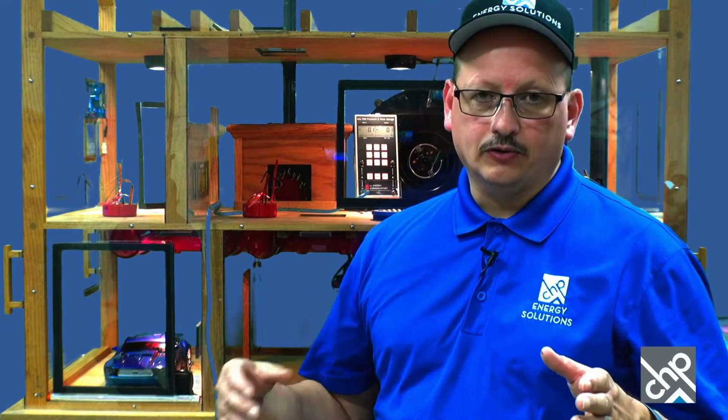So what I did is I set up this dominant duct leak test, and I measured the pressure. All I needed was a manometer. Like I say, I turned everything off, did the baseline, turned the air handler fan on, and we were at -5 just from turning the air handler on. So it turns out we had a supply leak. This in particular was a manufactured home, and they had put a package unit on for the heating and cooling. So it's basically two ducts that come in, and one went to a return, but one went to the main supply line that went down to the manufactured house.